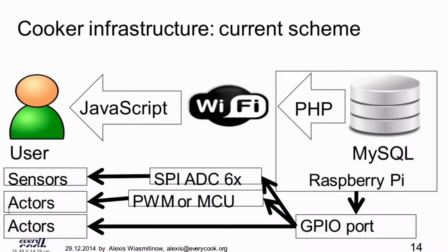A precise analog to digital converter is also needed, especially for the scale. We tried many things, but below 24 bits ADC resolution, a scale is quite tricky to make. But there are chips available and we can read them over SPI. So we have the load cells, the pressure sensor and the temperature sensor going over that ADC.